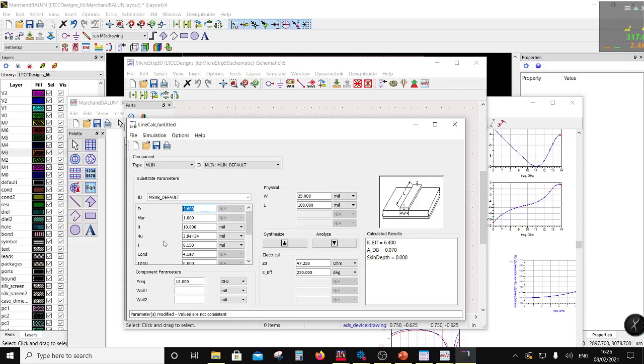Okay, so epsilon r is 5.92, and height of the substrate is 379 micron. Thickness is 9 micrometer. This is 5.86 and tan delta is 0.02, and I'm interested in 80 or 90 ohm line, which is 90 degrees. Want the result in micrometers. Synthesize.